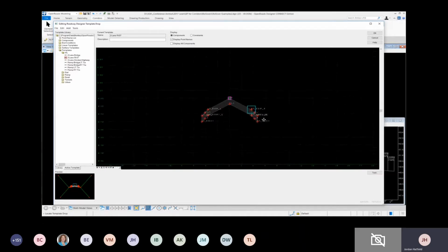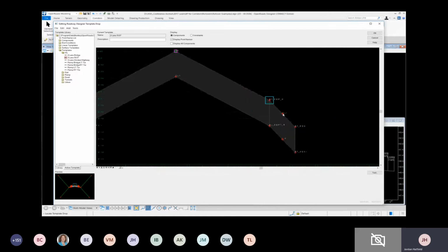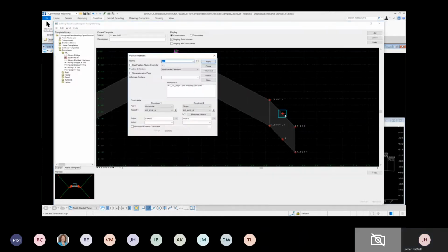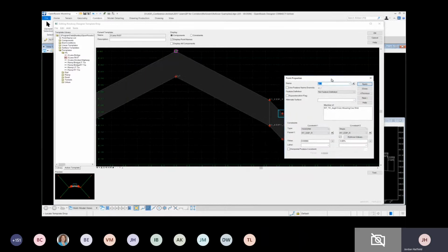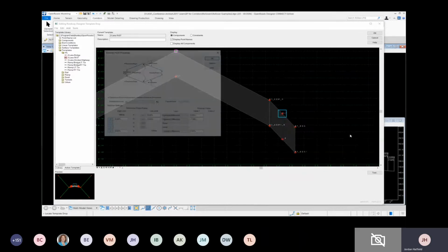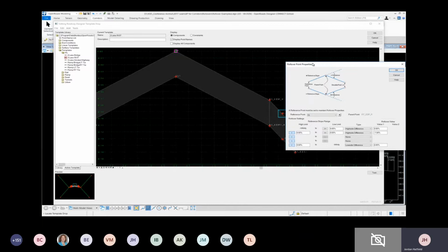So let's take a look and see how this was built. I'm going to set up my view to show this, and I want to show this in a way where I can focus on rollover and see this side there. Okay, so from this point, we're again looking from the lane, from the CL to the road edge pavement, as mentioned right here. So when the lane slope is positive infinity, greater than or equal to 6%, the high side difference is 0. So basically, when it's greater than 6%, it's going to match the cross slope of whatever the lane is.